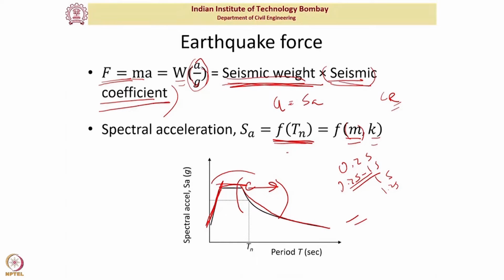And how would I change the time period? Mass or stiffness? Okay, but remember, typically the mass of a structure in a design is fixed. It is determined by the weight of the infill, beam and column weight, and live weight, and those things do not depend on the structure. I mean, it depends somewhat on the structural properties, the geometric properties, but overall, there is not much you can do about the mass. But what you can do is about the stiffness.